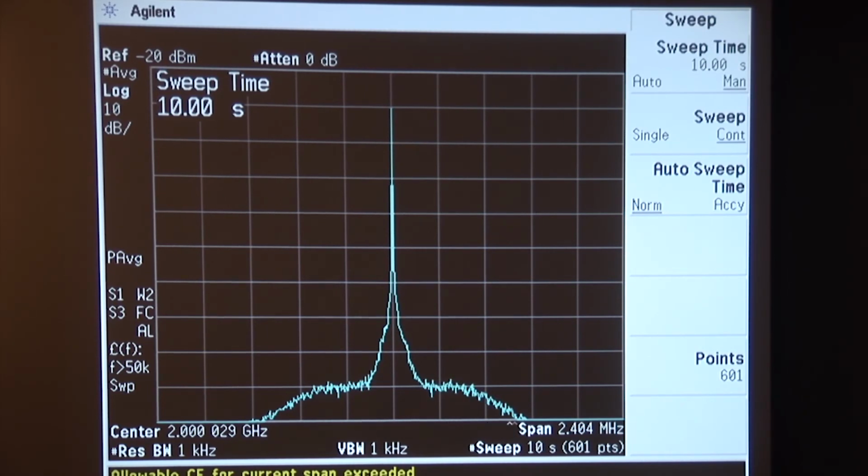we're still taking 601 kilohertz measurements across here, but we're spanning 4 times that much spectrum, and look what happened. Now the measured power has dropped down to minus 30 dBm. What's happening is none of our data points that we're using for this measurement are in fact landing right on the frequency of this carrier. And as I said, this is the so-called picket fence effect. It's something that we would normally strive to avoid when we're doing spectrum measurements.